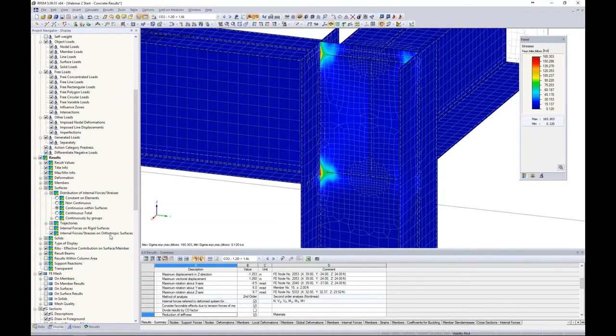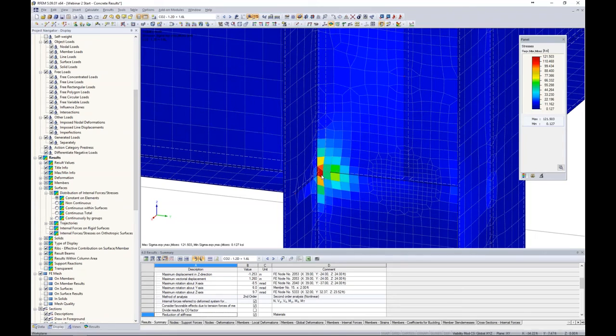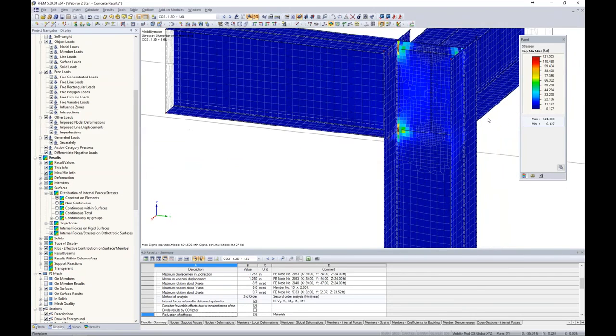Again, with my AISC Advanced Steel Design webinar, I did an entire hour dedicated to a connection just like this, and I go into much more detail, but obviously we're almost out of time today. The only thing I want to show you is that rather than tying it together with this smoothing algorithm, we'd rather view our results under our display tab in our project navigator. Under surfaces, for the distribution of internal forces and stresses, we'll view this as constant on elements. Now each particular FE element has its own contour, and we're not trying to tie those together, and our stresses went down from 160 to 121. They're still high, but you can see what a difference that makes.